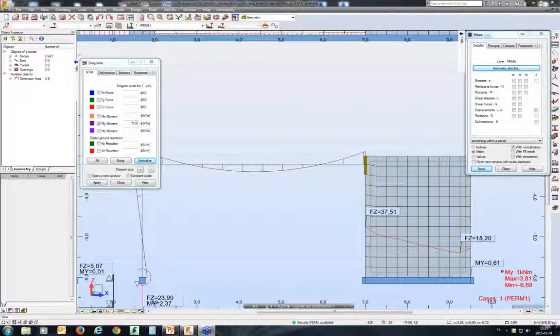So definitely, if you think that you can correct inaccuracy in the model by just putting a large tolerance, you may actually make things even worse, because the results that you obtain are entirely incorrect, calculated for a model that you actually can't see, which is different to what you entered.